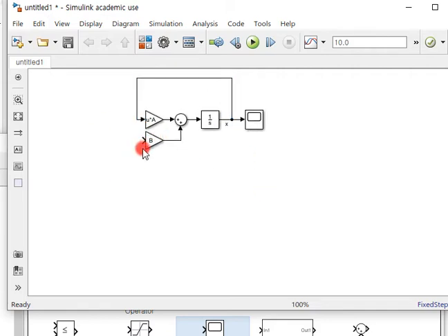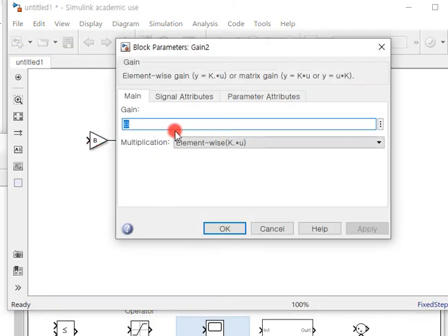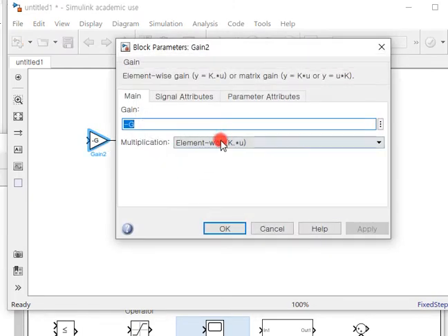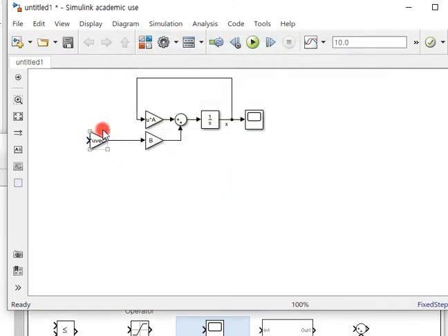We designed the U using state feedback, and we can obtain the control gain using the LQR function. So I set the LQR function output G using a gain block.